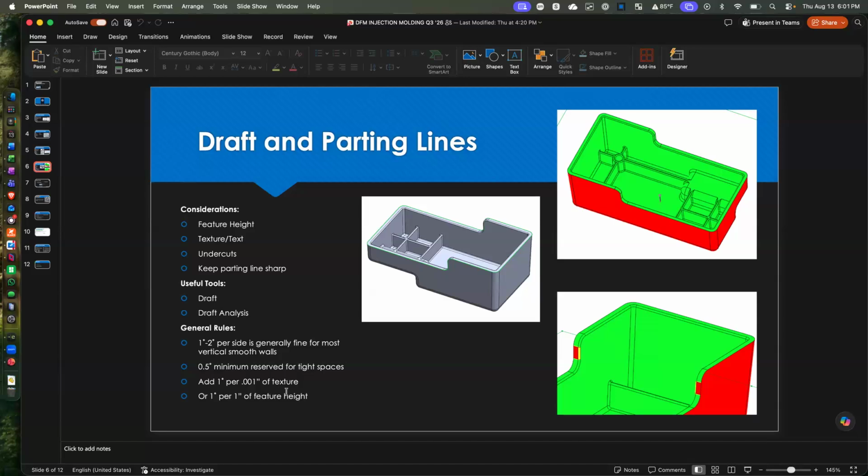So if you need a straight bore hole, those can often be done with 0 draft with all the features around it. But you do still have to be careful, because if your bosses have draft but your hole doesn't, your wall thickness goes back to the wall thickness problem, right? You can end up with the wall thickness getting too thick and maybe having sink issues and other things.